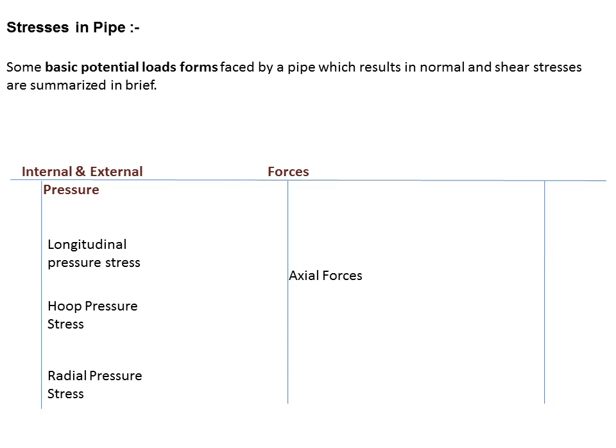Forces leading to the axial stresses and the shear forces. The axial and the shear forces lead to the stresses in the piping system and the components. And the load form is in the form of moments, wherein we have a bending moment and the torsional moment causing the stresses.